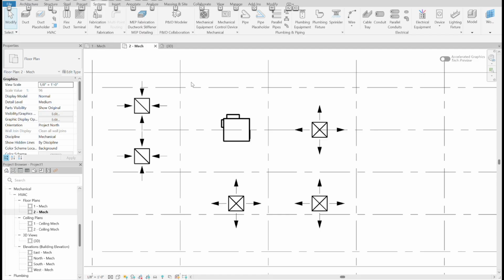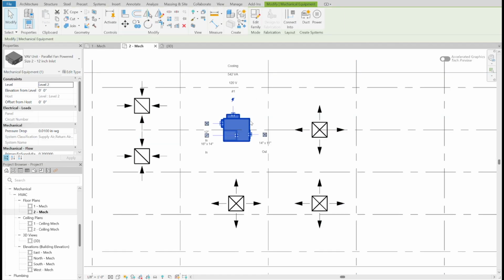So now I have created a clean version of the air handler unit and AC terminals without any duct. I just removed the ducts. Now I want to show you how Revit can automatically generate a layout for us. So first, let's select the air handling unit, and from here, let's go to create a system duct. And let's give it a name. This is about a supply air. Yeah, that's right. Let's name it the supply air for game room.